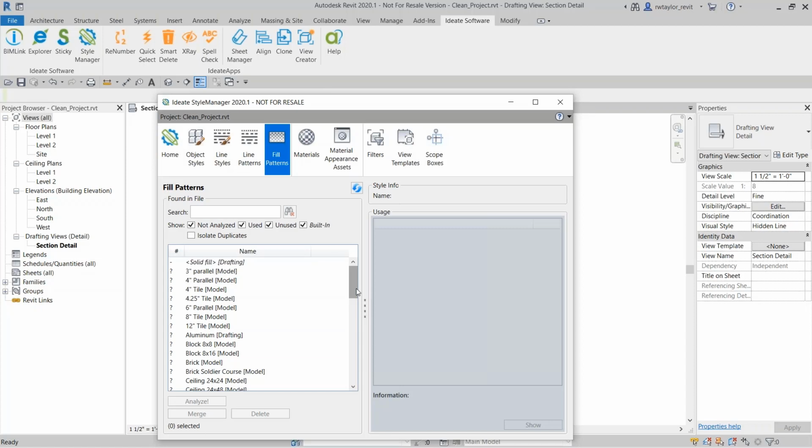Another question from Vita is, how does it work in regards to worksets? Well, you do have to have the permissions to change elements. We've done a lot of work with worksets and worksharing. So if you have, let's say, one CAD file that is locked by worksharing, and you just made a change to 50 things, it will change all those 50 things, but for that one CAD file, it will say this is locked by worksharing and it can't make a change to that.